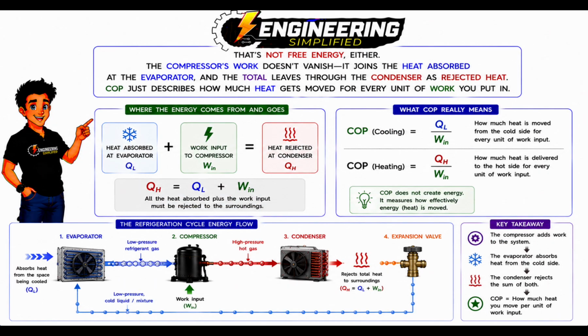That's not free energy either. The compressor's work doesn't vanish. It joins the heat absorbed at the evaporator, and the total leaves through the condenser as rejected heat. COP just describes how much heat gets moved for every unit of work you put in.